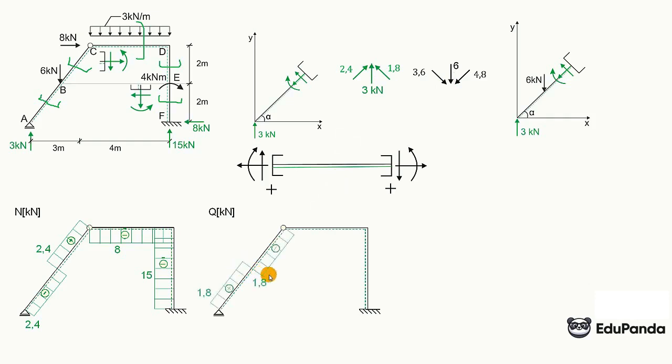Then we go to the vertical rod from the bottom, and here we look at what shearing forces we have. The shearing force is this 8, and no matter how we shift the cut to the end, there is no other shearing force than this 8. Its direction is a positive direction in this section. So, over the entire length of the rod, we have a positive 8. And now the horizontal rod.